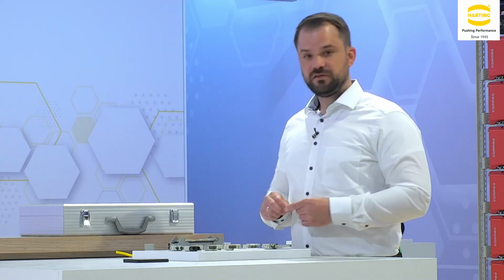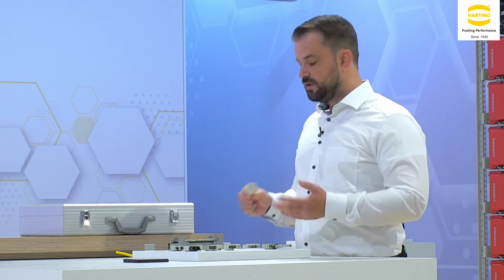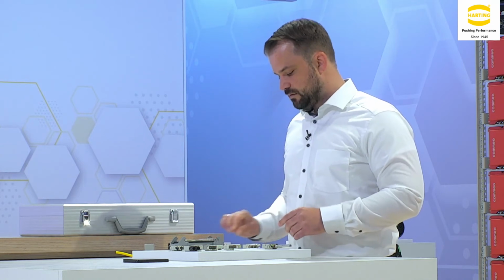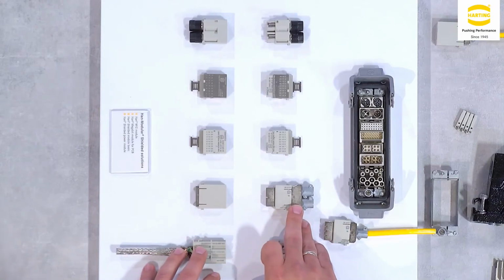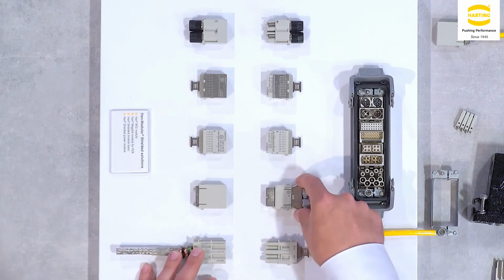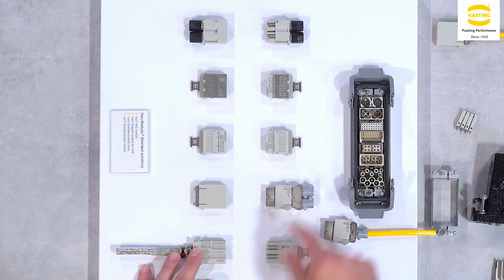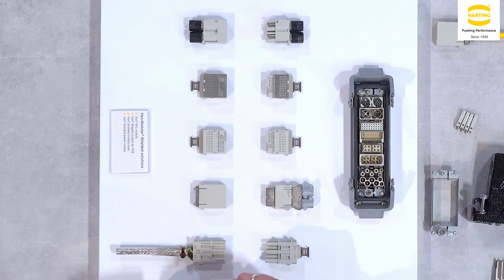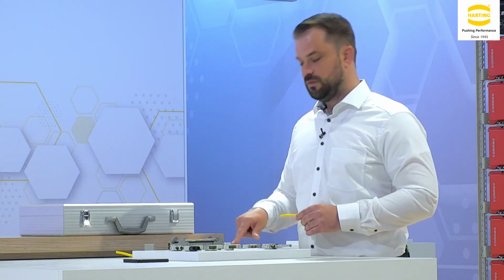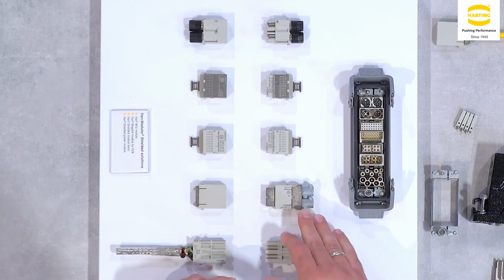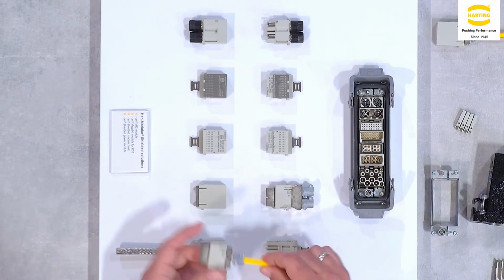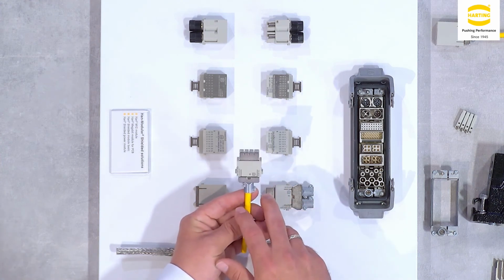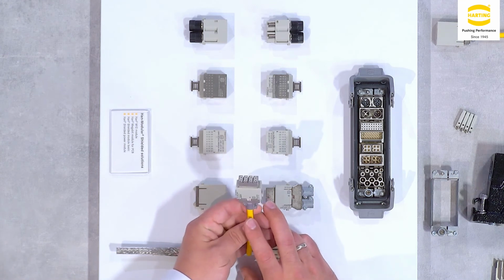The more sophisticated way to transmit the shielding within a connector is our metal modules, and these start with the megabit module that we see here. So we see our zinc die-cast body here, where the isolation body is implemented, and we have different modules for different categories. The megabit module can be used for category 5, and then we have the gigabit module, which can be used for category 6, category 7, and now also reach category 8.